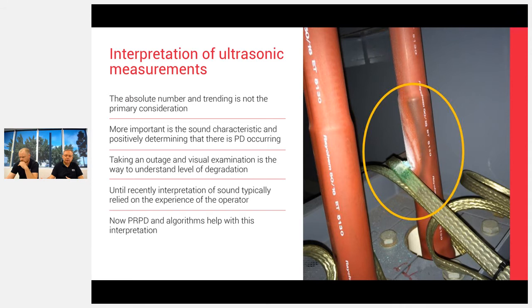Previously, it was a lot of just user experience. Does it sound like discharge? Nowadays, with the PRPD and the algorithms, that helps us interpret, is it single phase, is it multiple phase, and also what type of discharge we look for, and the positivity of, is it PD or is it noise? So that's how we trace things through on an ultrasonic level.